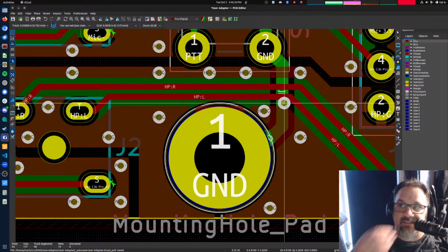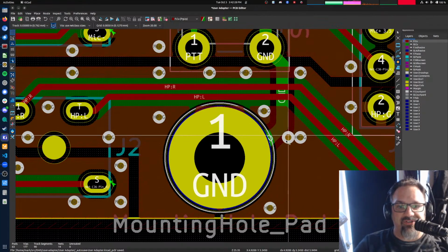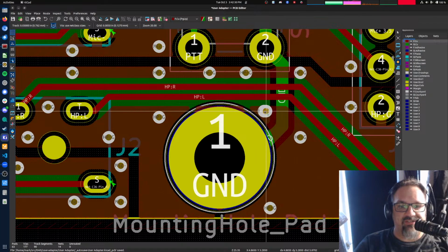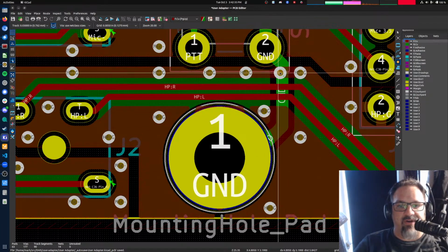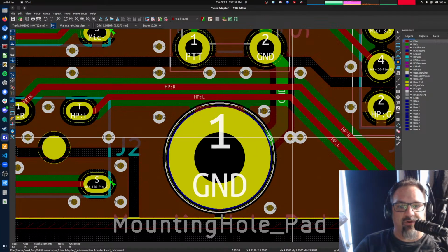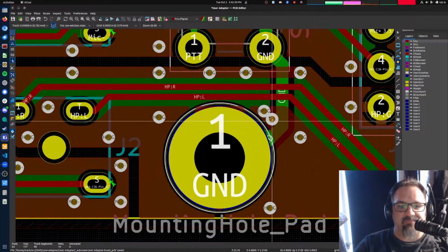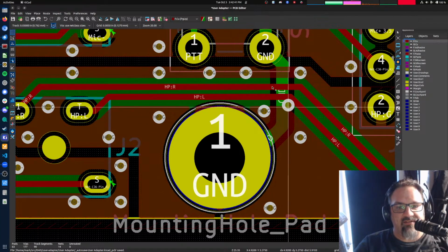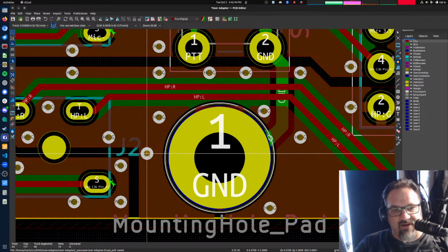Yeah. He says, mostly, yes, that explains it, but it took him a while to understand why I bulged it out. I bulged it out to the right so that I have a space to put this via right here to connect this ground to that corner there. Because otherwise, we still only have that one little path, right? The whole point is to connect this part up to here and create a second attachment point for that ground.